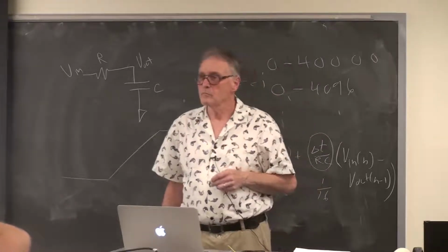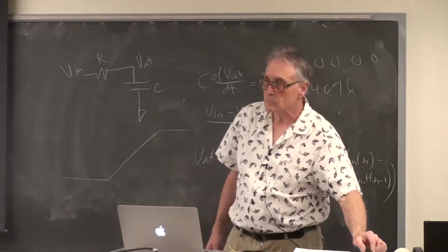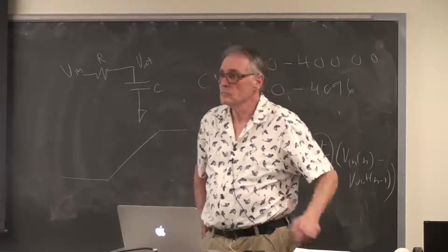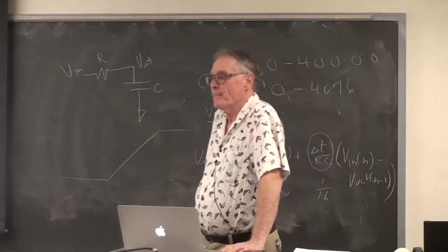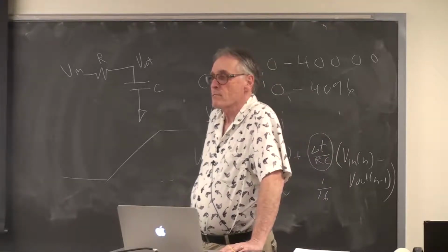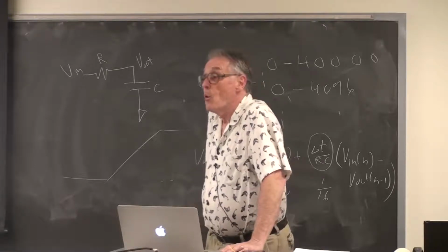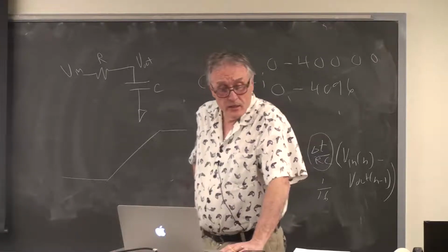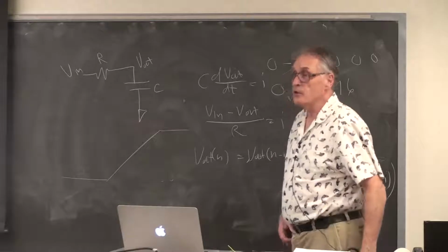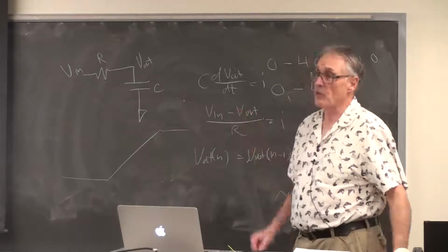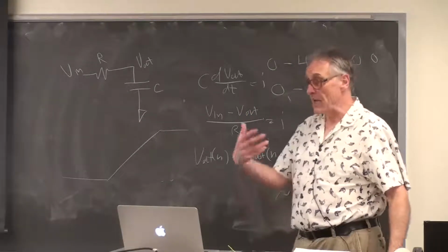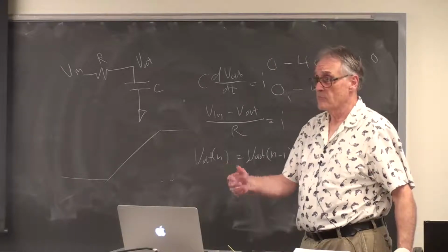Wait, so if we're doing KI in terms of a shift by some number, then how exactly are we going to be inputting that? Because it's not something that you can discretely input the same way you could input the values for KP and KD. Okay, so let's say that you do it as a shift number. You could just enter the shift number rather than the actual value.